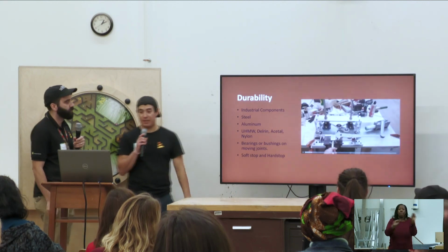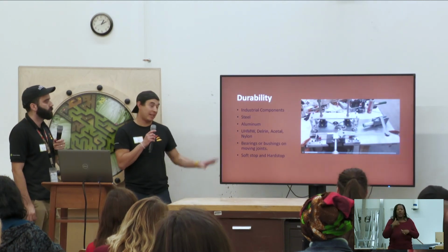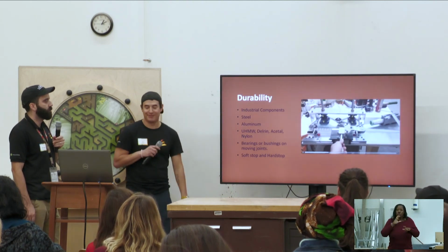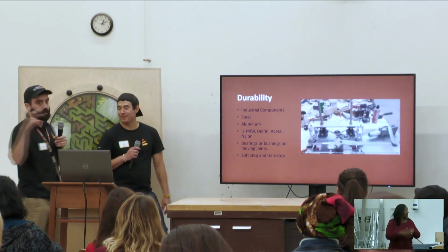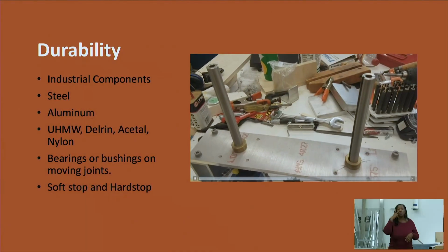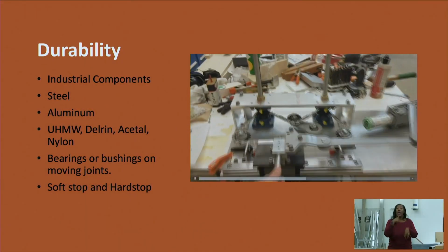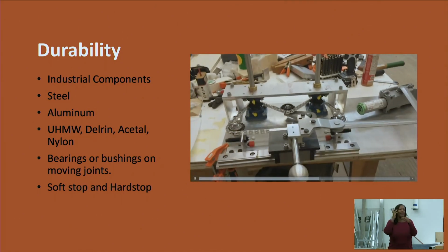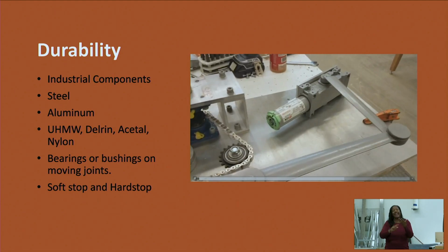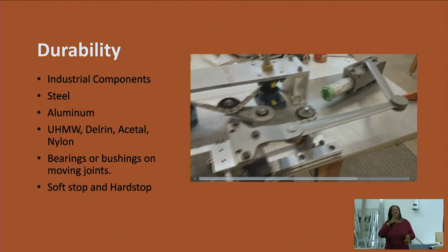It was super cool to see and amazing how it got engineered, but that's a super complex solution to turning two little rocks around. Yeah, and for the return, you see we use a door return. That mechanism pushing back is what you see at the top of a door in a building. And that was because the interactive needed a reset. Often if you can design something without a reset, it drastically reduces the complexity.